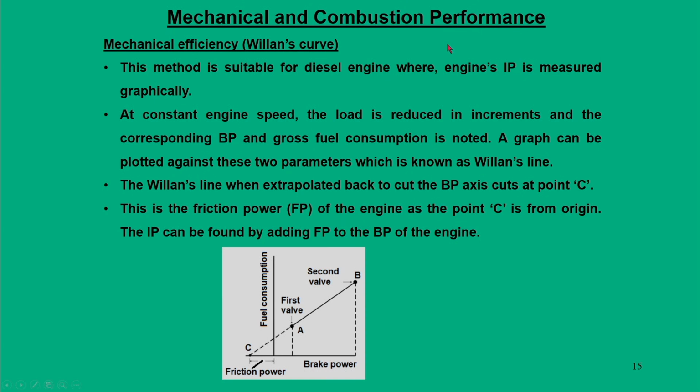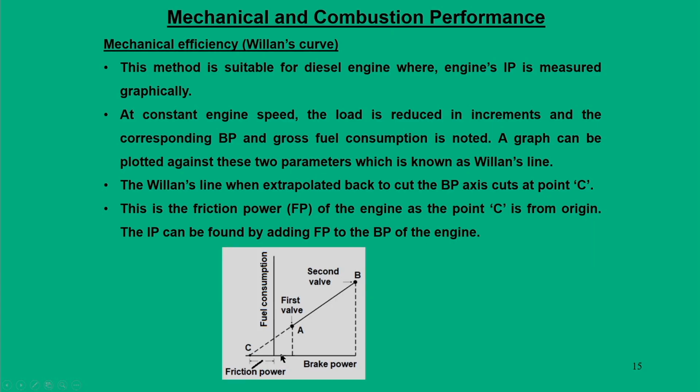The last one is known as Wilson's curve, and this is mostly applied to diesel engines, because in the diesel engine we have provisions for cutting off the fuel through the fuel injector, and it is only applied for that concept. If you look at this particular plot, it is a plot between fuel consumption and brake power.